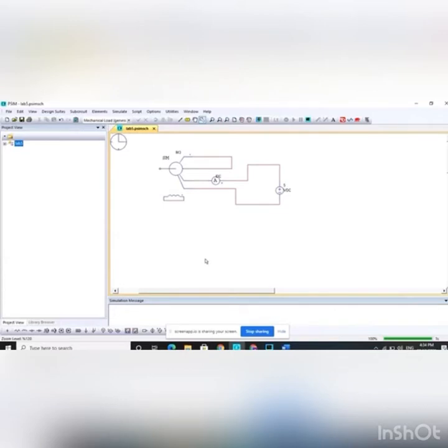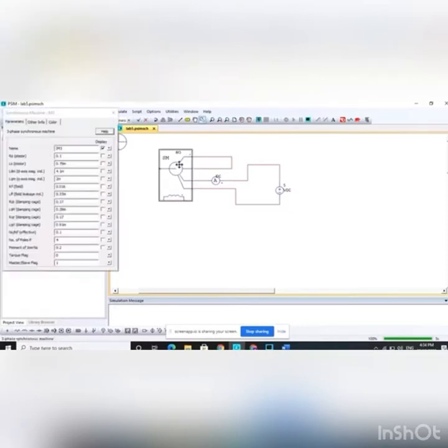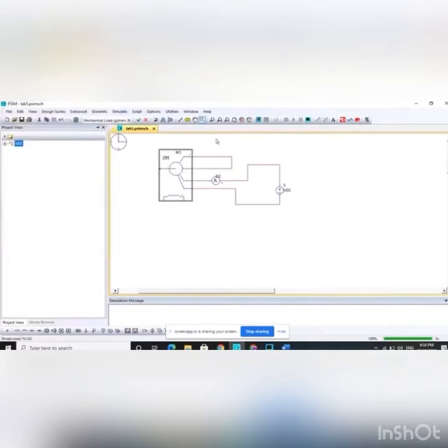Today I would like to present my part, section A for lab 5, part 1, the 3-phase synchronous generator. In this part we have to measure the resistance RA of the Y-connected stator winding. We use a 3-phase synchronous machine and put all the values into it. The values are already provided. Then we use the DC current and DC voltage.